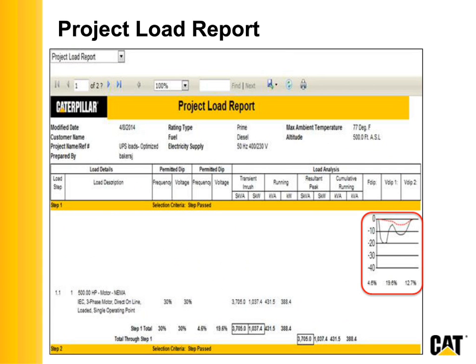we're looking at optimizing your genset. And so what we do is we box the values. Say you've got, SpecSizer will size up to 99 loads and 99 steps. Say you've got a sizing that's 40 load steps, and you would like to know for your starting KVA, what load step should you work with to reduce your starting KVA, to reduce the size of your alternator.